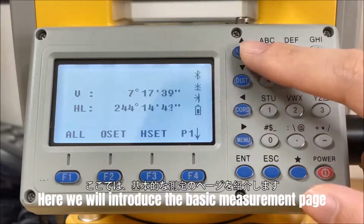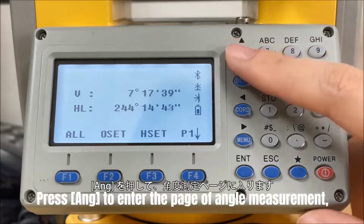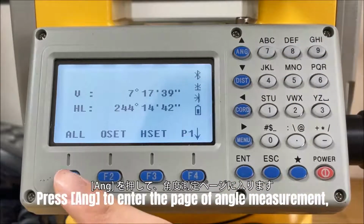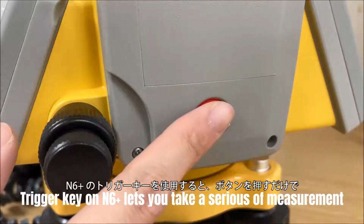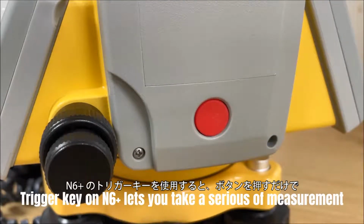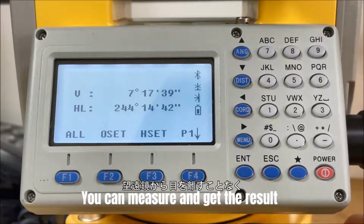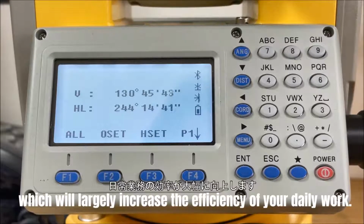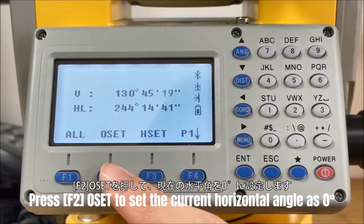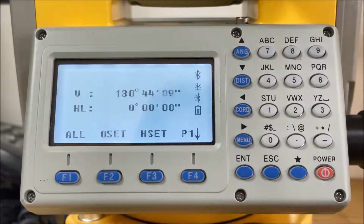Here we will introduce the basic measurement page of the N6 Plus total station. Press Angle on the keypad to enter the page of angle measurement. F1 is for measure and save. The trigger key on the N6 Plus lets you take a series of measurements by a simple button press. You can measure and get the result without taking your eye off the telescope, which will largely increase the efficiency of your daily work. Press F2 to set the current horizontal angle as 0 degree.